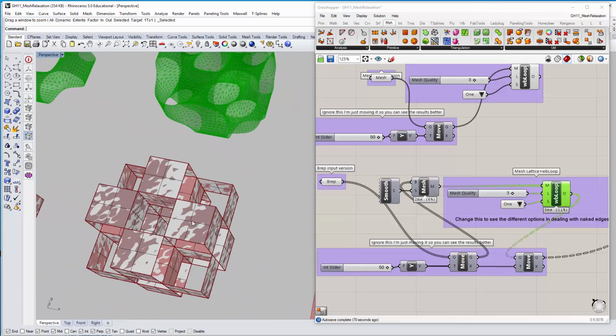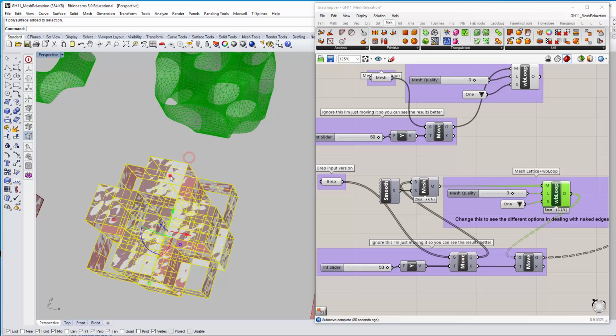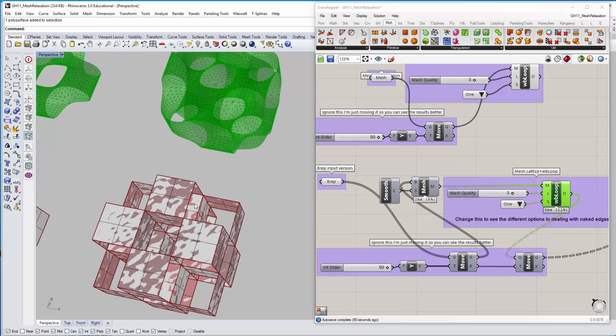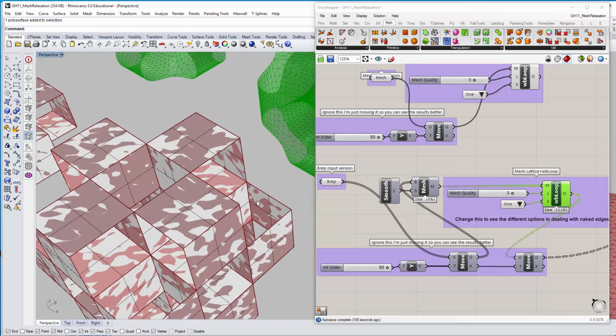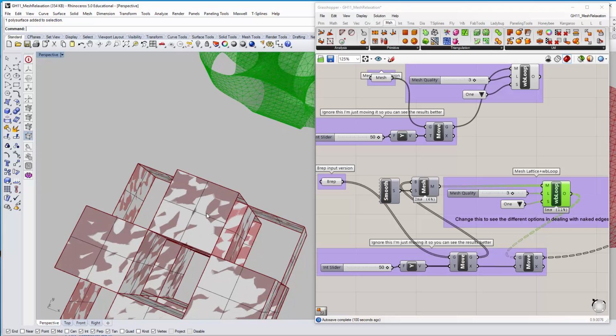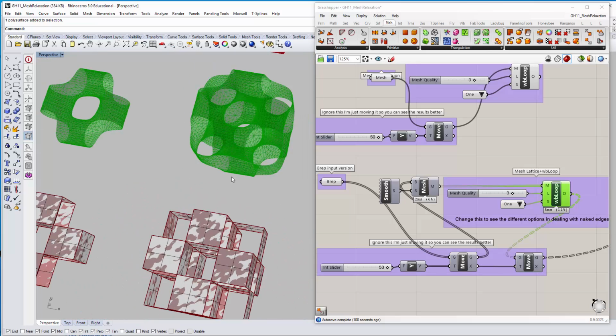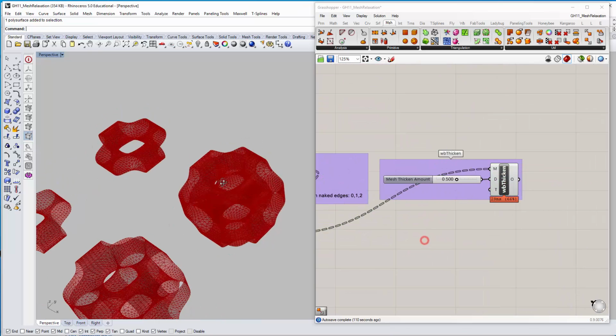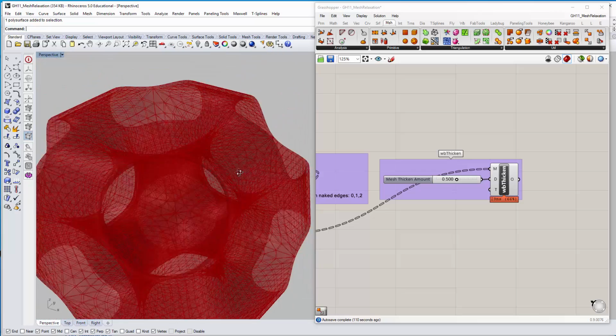Okay. Now this is somewhat contingent on the mesh face or the poly surface faces being somewhat consistent, both in terms of how they connect. You could probably warp or distort this a little bit to get something a little bit different that has varying sizes and whatnot. But you would have to stick to some pretty strict rules as far as making sure the edges are connecting a very specific way, that the topology stays the same for this to work. And then obviously you can do the Weaverbird thickness to give it an offset thickness.